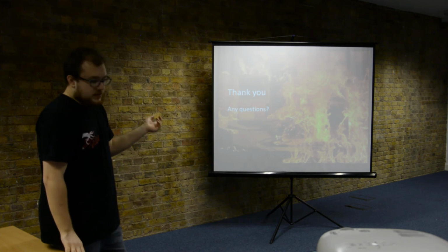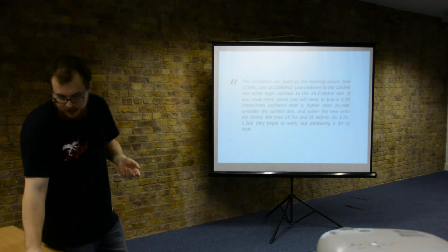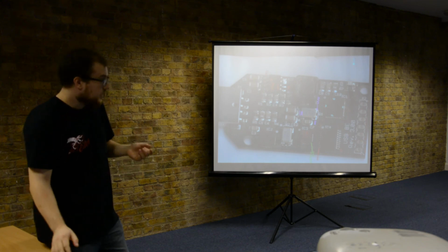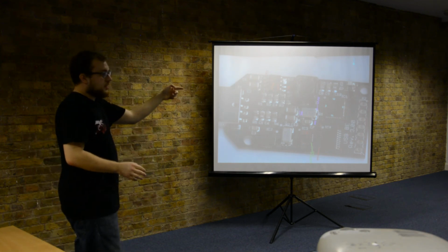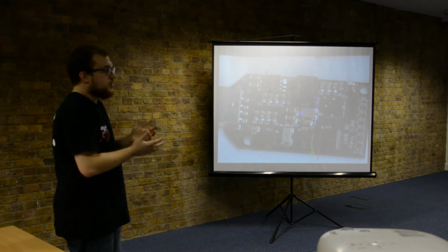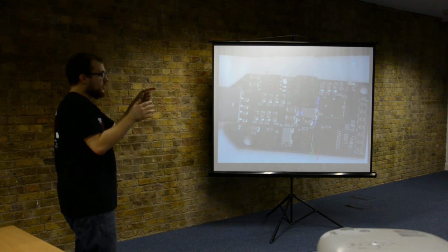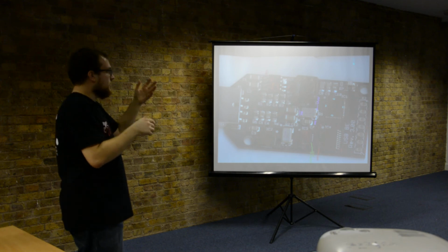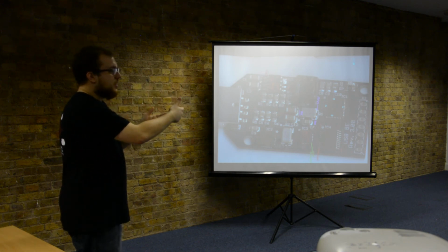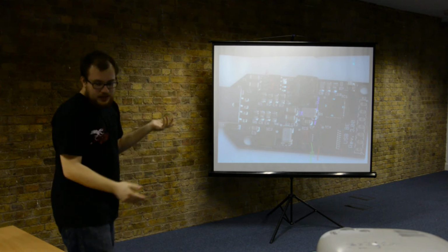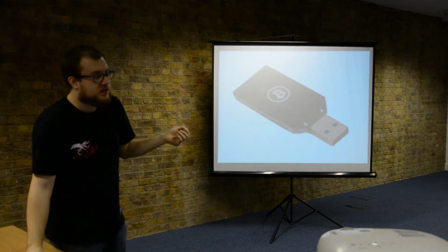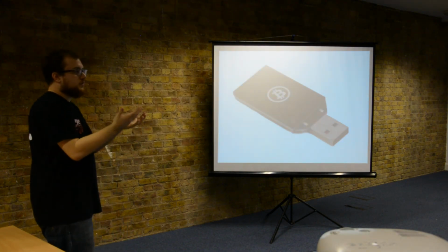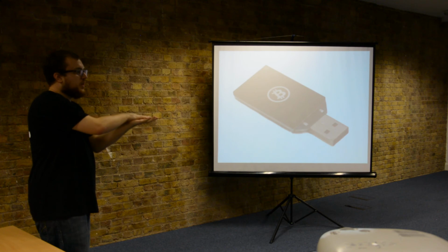Most of these new devices, for instance this ASIC mining chip, sticking a heatsink on top is not actually the best way to cool it, because it's a QFN package and there's a big thermal pad underneath it. So most of the heat is dissipated on the circuit board side. That's why they have a heatsink on the other side of the board rather than on top of the processor itself.